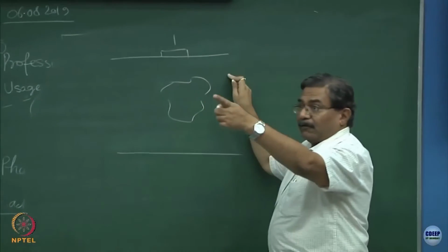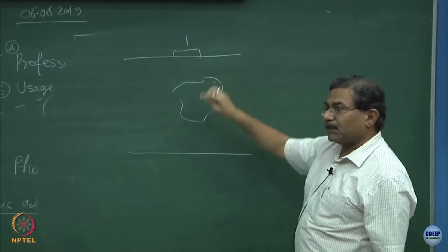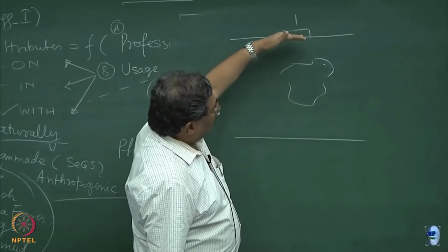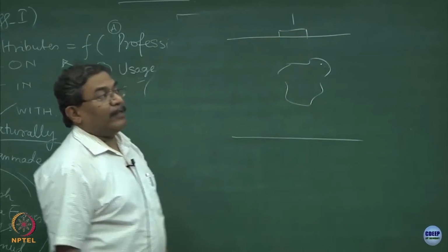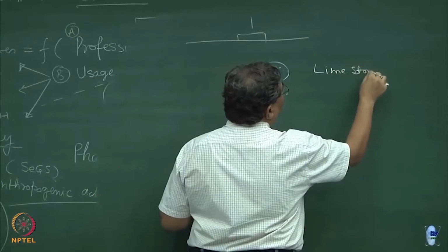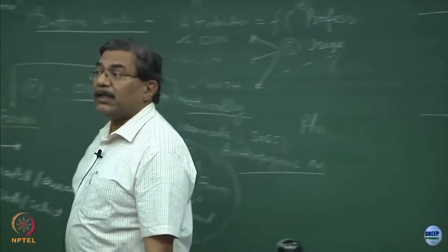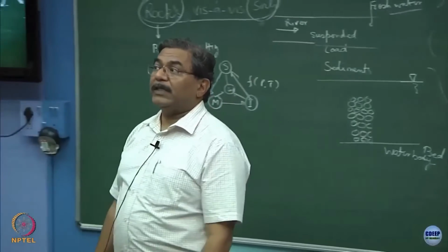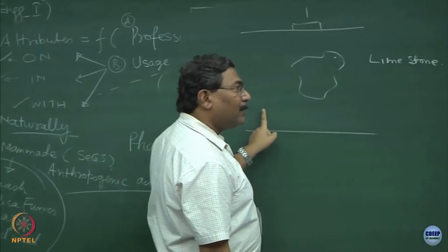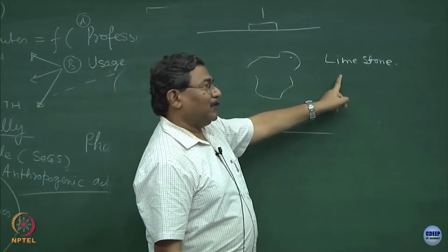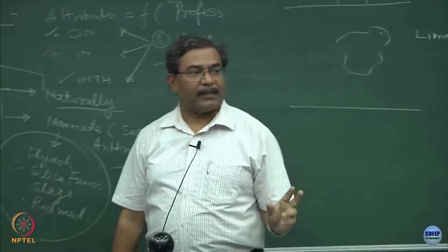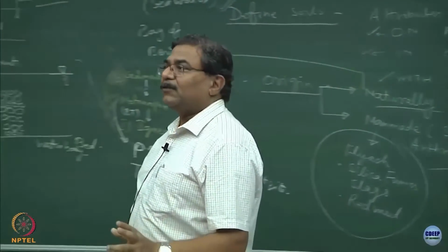Look at this, another example of the chemical process. Coming back to the question you asked, these types of subsurface deposits are very notorious. Mostly they are limestone, and they are sitting in the coastal areas. Clear? What does seawater have to do with this? Now, this seawater ingresses into the foundations or the strata and has a tendency to eat up the limestone and create cavities under a very specific condition of pressure, temperature and humidity. This is what is known as lime dissolution.